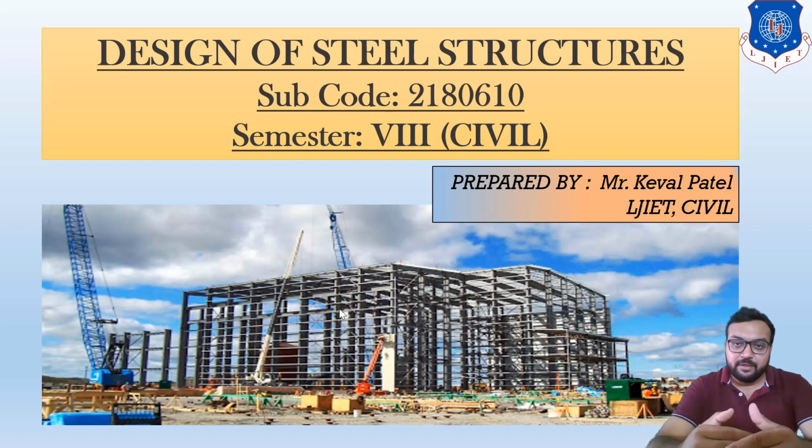Okay. After that, in the second type of connections, you all know that the load transfers from secondary beam to main beam and main beam to column. So whenever the load transfers from secondary beam to main beam, there is beam to beam connection in steel structure, and whenever the load transfers from main beam to column, there is a junction between the main beam and columns.